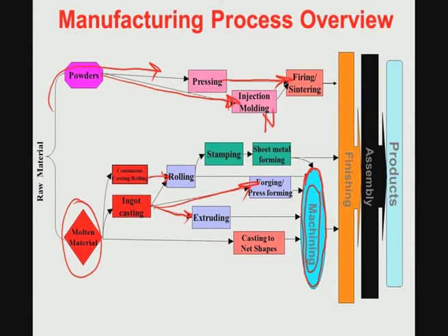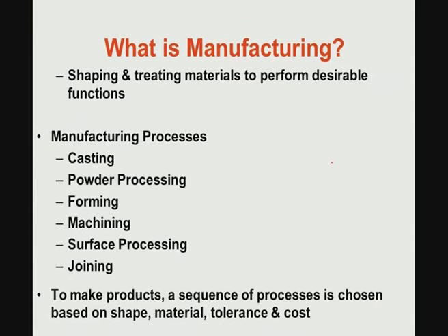So, this powder injection molding, the advantage is that you can get more or less a near net shape product. Now, near net shape product is somehow very difficult in a one step process in case of the molten metal based route, whereas with powder injection molding you can have a specific mold shape, so that you can get the implant exactly in a particular shape and size.